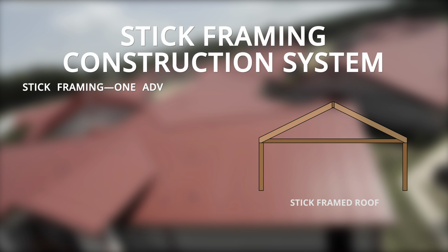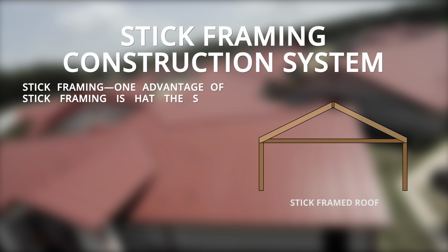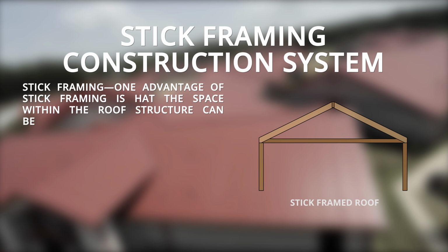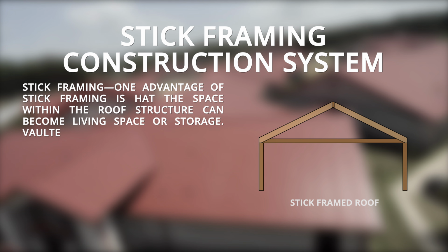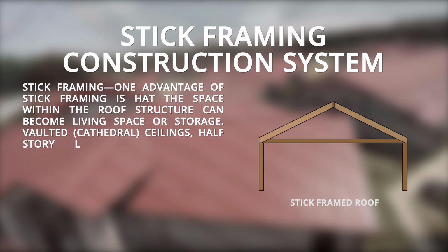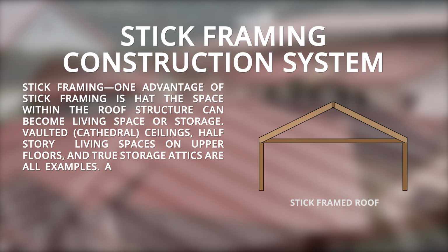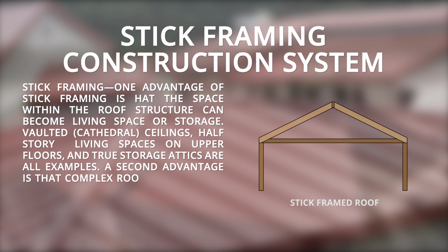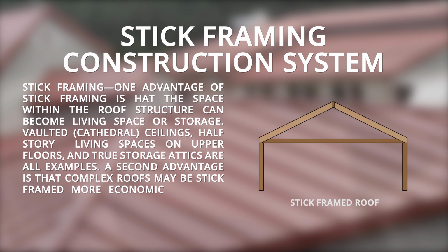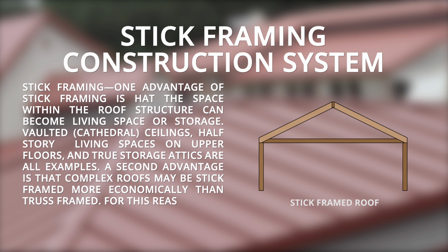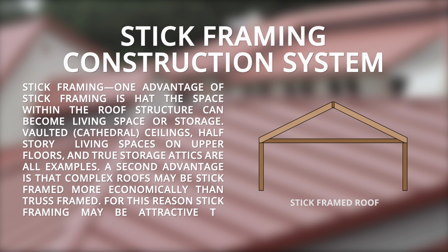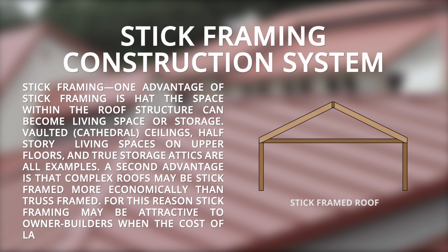Stick framing construction system. Stick framing. One advantage to stick framing is that the space within the roof structure can become living space or storage. Vaulted, cathedral ceilings, half-story living spaces on upper floors, and true storage attics are all examples. A second advantage is that complex roofs may be stick-framed more economically than truss-framed. For this reason, stick framing may be attractive to owner-builders when the cost of labor is not a factor.